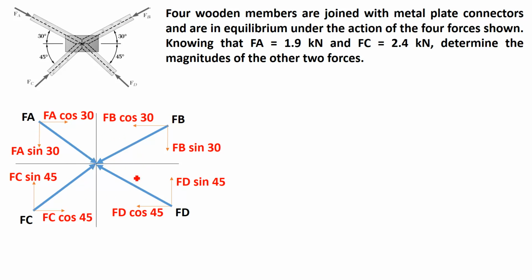Now according to the corrected quadrant of the force, Fa is in the fourth quadrant, so we have resolved this force into xy components. Fourth quadrant means x component is plus, y component is minus. The angle with respect to horizontal is given as 30 degree. So horizontal component is cos, vertical component is sine.